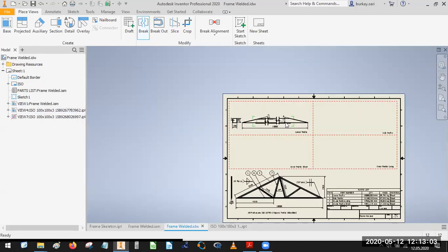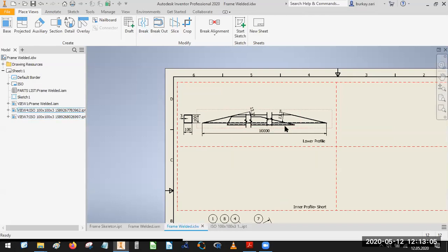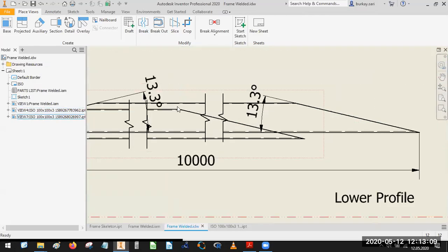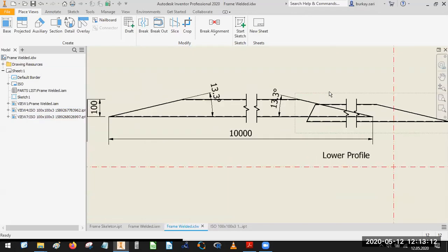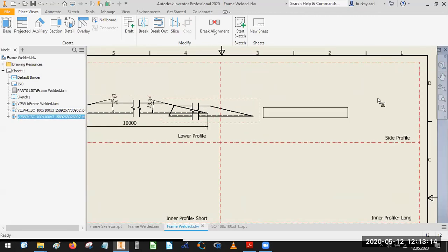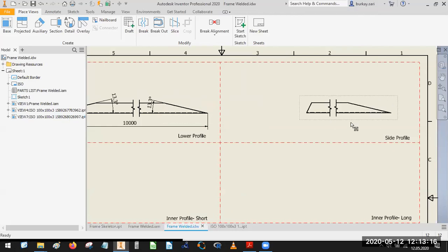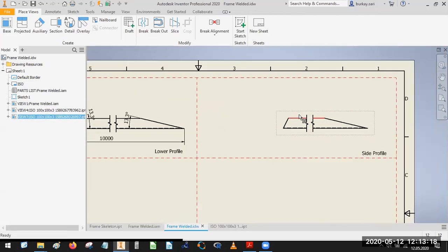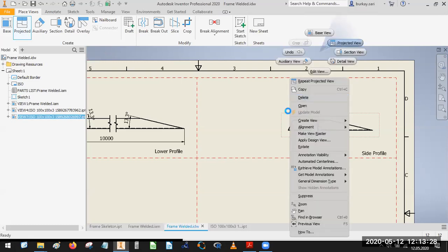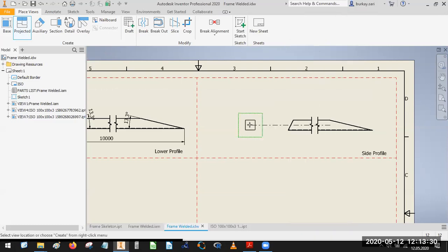As you see, we have a very short profile. I would just like to select this short view to sideways. You can also do something somewhere else in your figure here. I would like to have a projection view. Okay, right click, projection, which is a sideways. Right click, create.